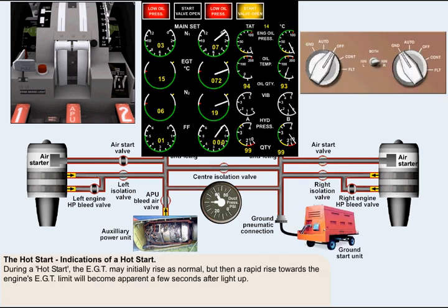It's really only possible to determine that a hot start is happening by comparing its indications to those of a normal start. The EGT may initially rise as normal, but then a rapid rise towards the engine's EGT limit caused by a hot start will become apparent a few seconds after light-up.